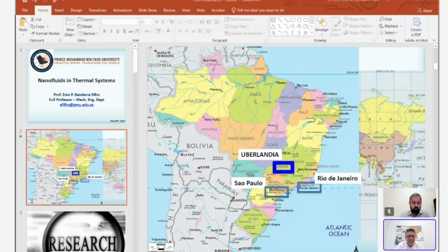So just to have an idea, what is nanofluid? Most people understand this, but most of them think it's nano because it's a very small fluid. It's not a very small fluid, of course. It's like a colloidal dispersion. In general, nanoparticles from 1 to 100 nanometers are dispersed in a liquid, in what we can call a base fluid. It's not like you have a powder or coffee or sugar or something like that that you mix with water, and then this makes a single fluid.